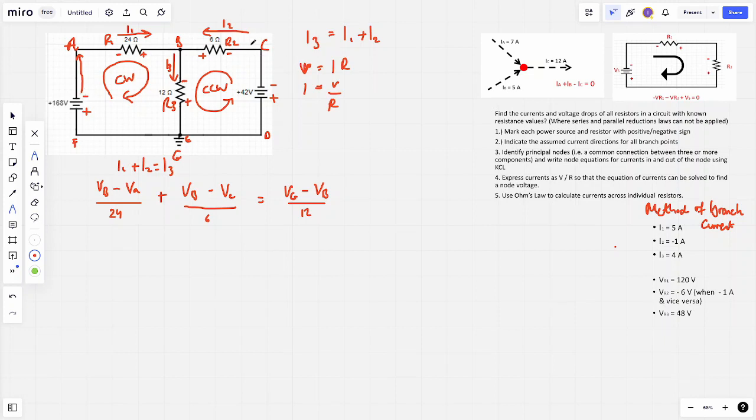Now if we look at C, again, there are no components as the electrons leave the battery, so it has the full voltage at VC, which is negative 42 as it leaves the negative terminal first. We're going to use these signs as it's really important to be consistent through our equations to get the right answer at the end. So VB, we don't know what the voltage is because we've got resistance in between, so we don't know what value of voltage is being consumed.